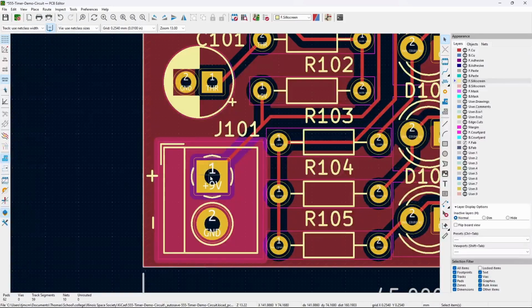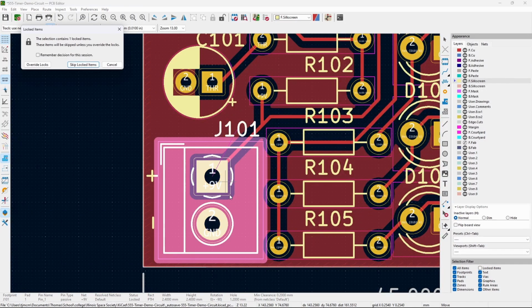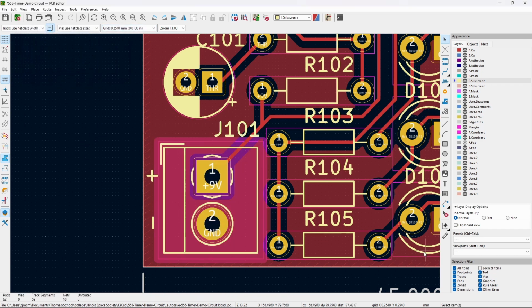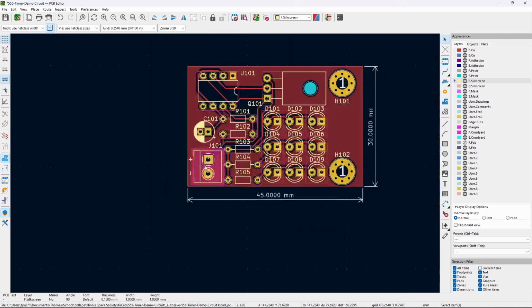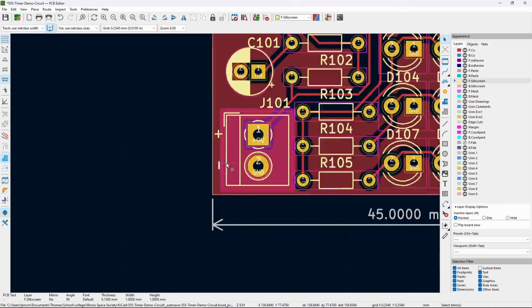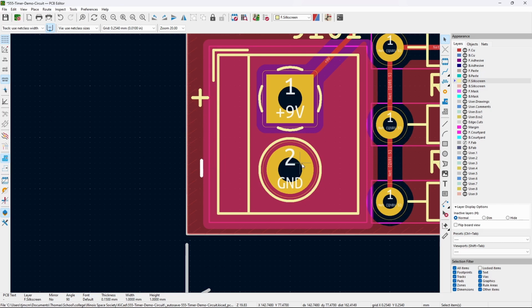So that'll make it so that we can't move this around if we want. We get this error here. So we can use that align tool from earlier with the mounting holes with this, and now the terminal blocks won't move at all if we try to align these. And so we do have to use that tool, we have to check this locked items box in the selection filter just so that we can select these together.